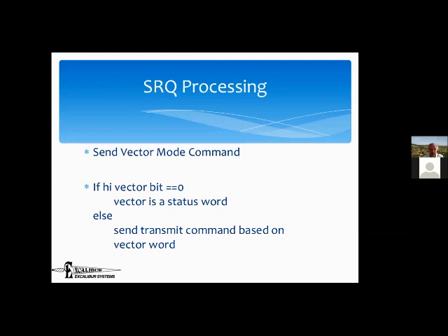Now the RT knows that it's subaddress 3 because he knows that the problem is a fire, right? It could be 4 other problems that have data in other subaddresses. The RT knows that it's the fire, so he's now telling the bus controller, listen, the problem here has information for you in subaddress 3, and there are 7 words of information. The bus controller then sends the next command, which is to the RT number of the engine, to subaddress 3, asking for 7 data words, and it's a transmit command.